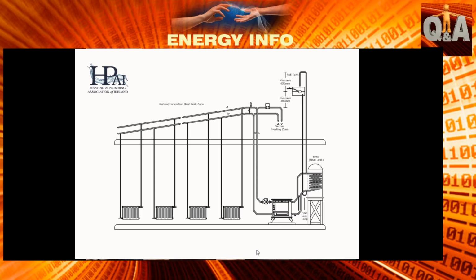In fact, you don't even necessarily have to have top and bottom connections. Those radiators will work perfectly without the pump operating. So if you lit that fire and it's installed in accordance to the diagram there, the pump is there as an added feature, but the system will actually heat without the pump. Every rad in that house and the hot water will heat without electricity. It's a very interesting system.